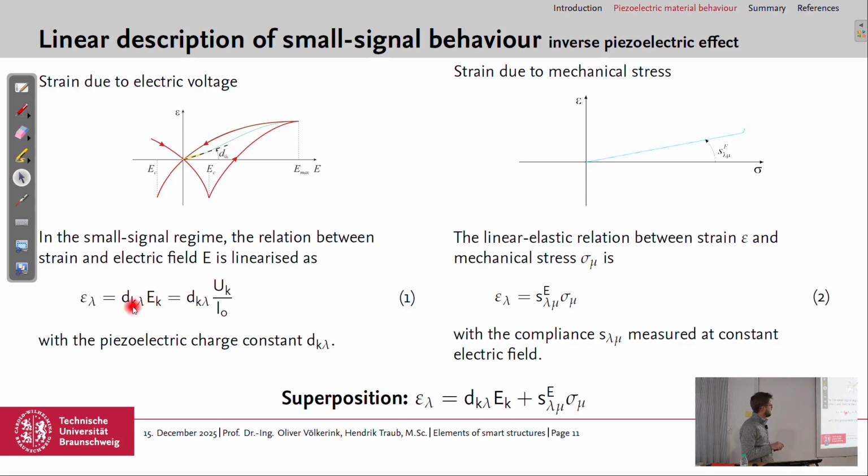And the electric field could also be expressed as the applied voltage divided by the distance between the electrodes. So strain equals piezoelectric charge constant times the electric field.